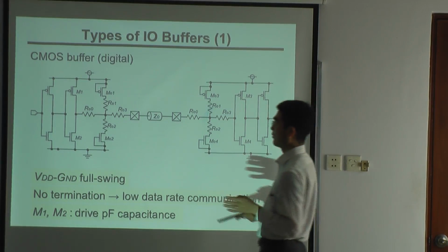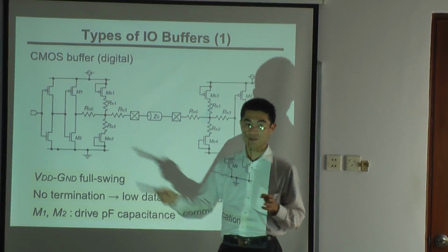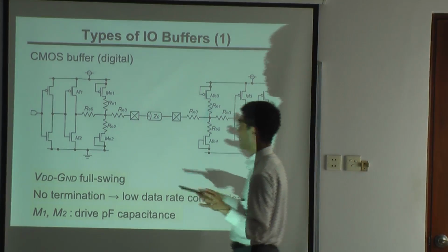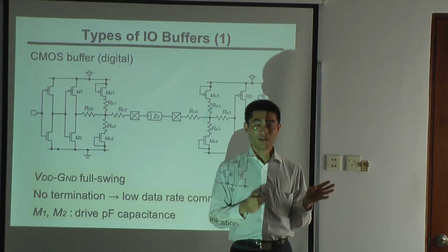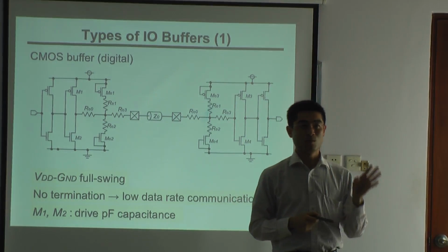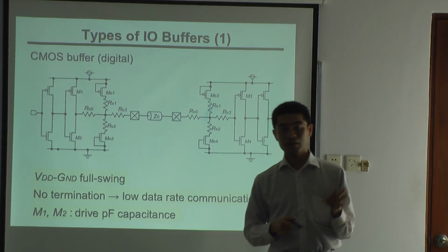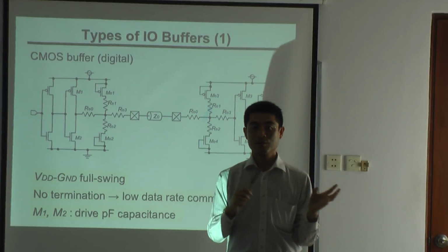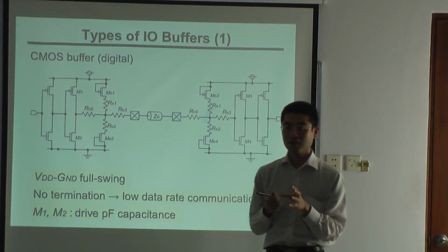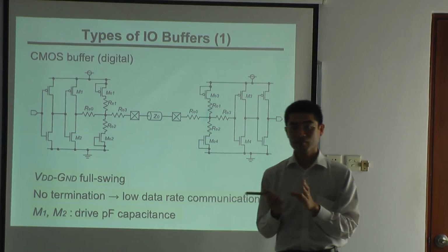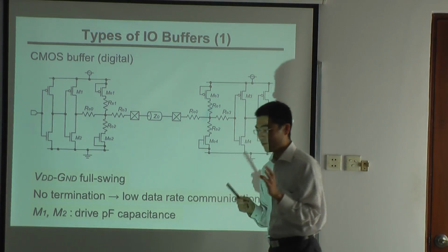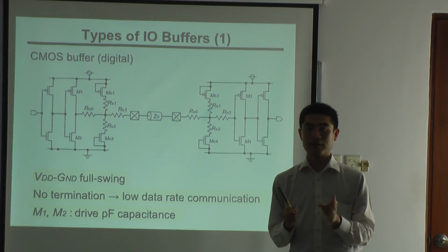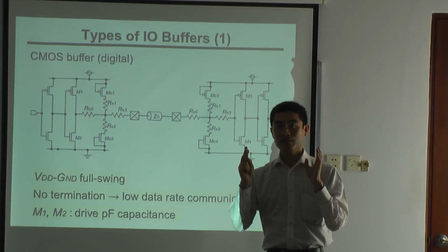Basically we have to put this. But for high-speed signals, we don't want to put resistors. So for high-speed signals, or for example RF input and output, we want to remove the ESD protection, because if it is there, we cannot meet the specifications. In such a case, we remove it, test ESD, and see if it passes or fails.